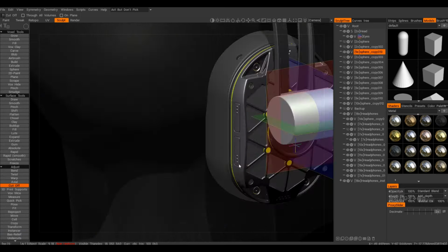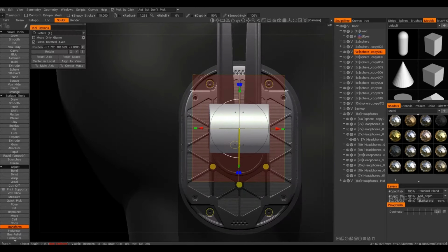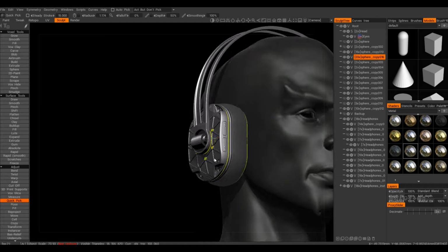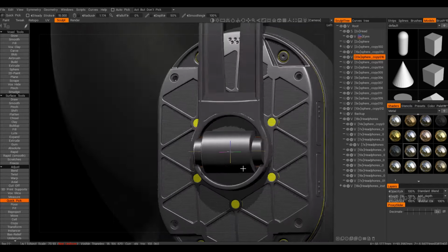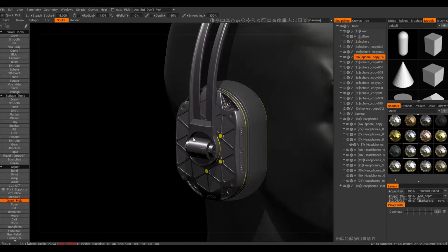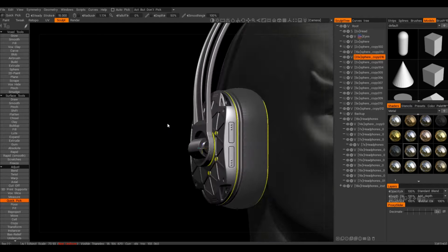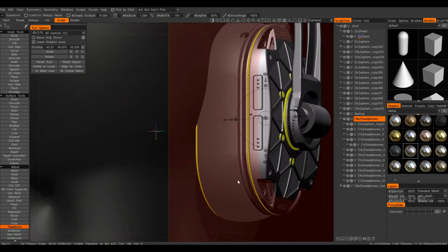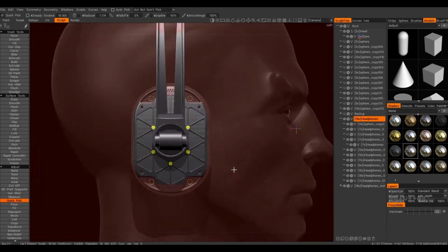So I wanted to create a cylinder, so I need to create these joints for rotation of the ear cup. So I can pretty much rotate it in 2 axes, and it's also a pretty bendy headband, which usually all the headphones are. So just stretch it. You can see a bit of a funny shading on the cylinder. It means that it's non-uniform volume, so I have to right click on the layer and make it uniform.